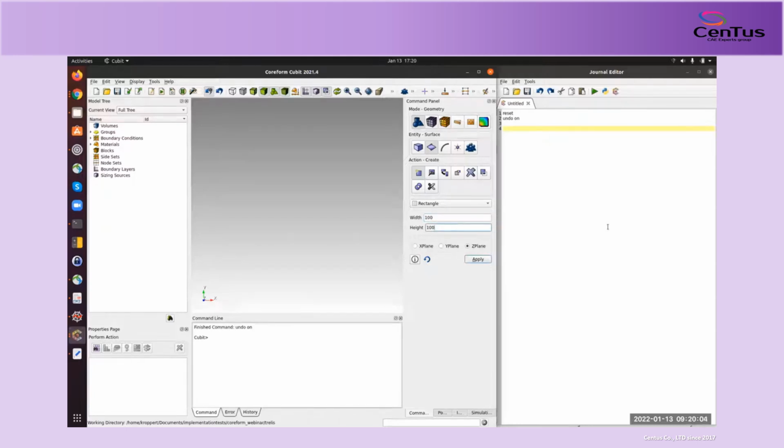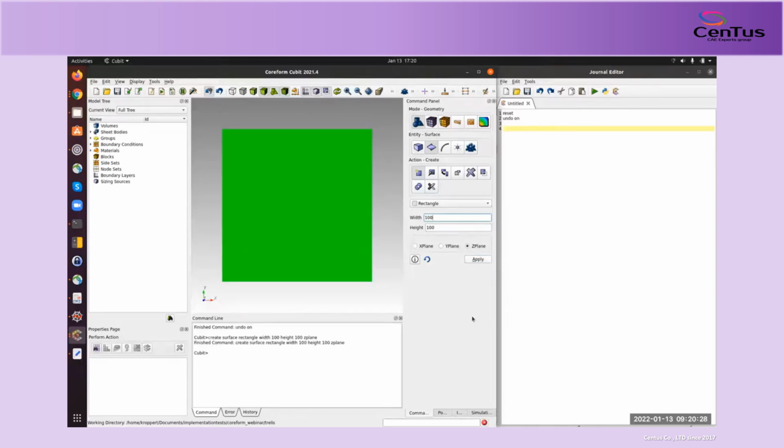So basically here everything is in SI consistent units, so it would be in meters now. However, I scale it down before exporting the mesh, by a factor of 1/1000, to have it consistent with our simulation software, to have everything in meters. Okay, let's click apply, and this is our air domain.